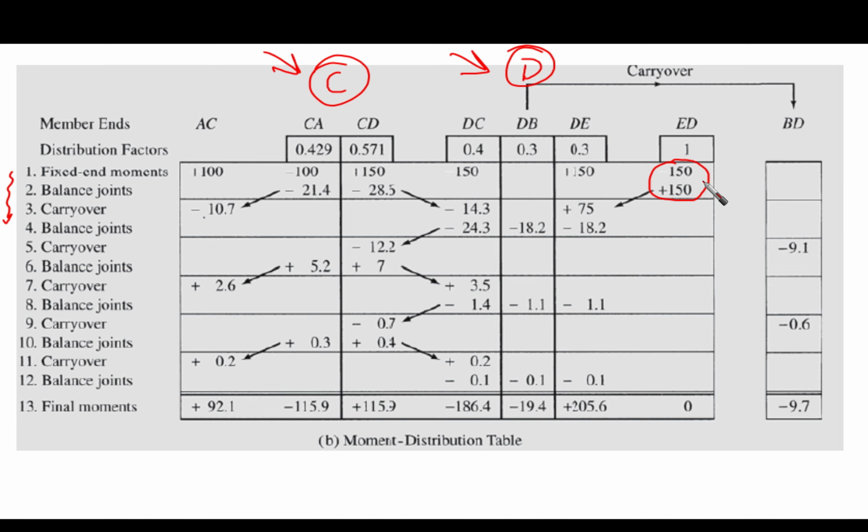If we have a hinged end condition or boundary condition, and we already used the 3/4 of the relative stiffness in our distribution factors, then you are going to balance it only once, and that's it. There is no carryovers, and you are just going to find that here the moment is 0, as we expected. Okay.